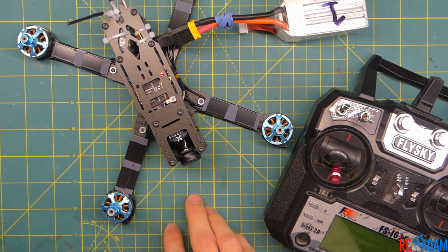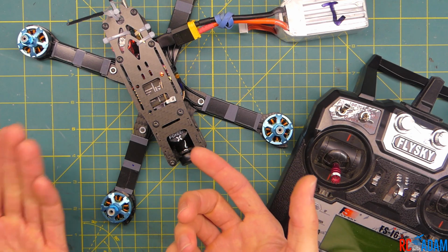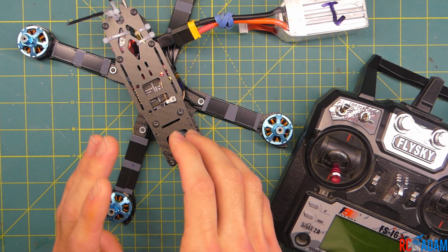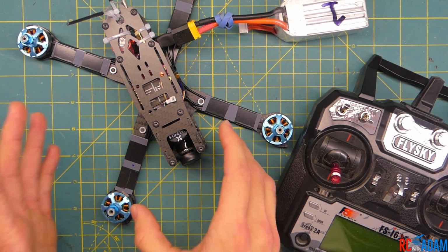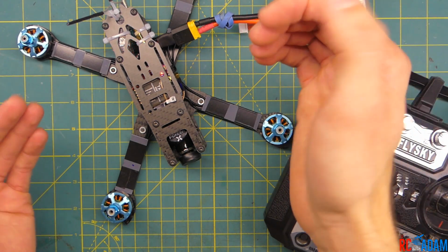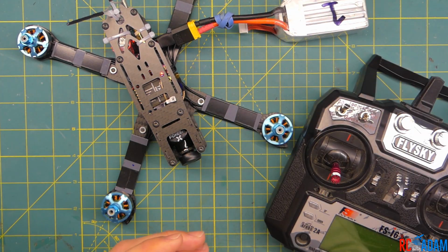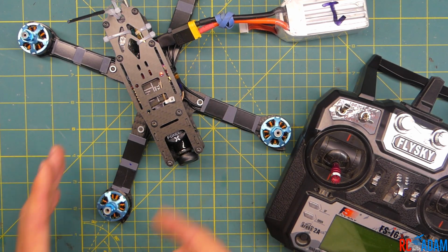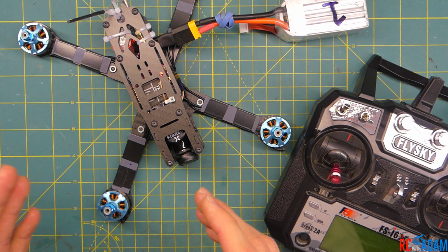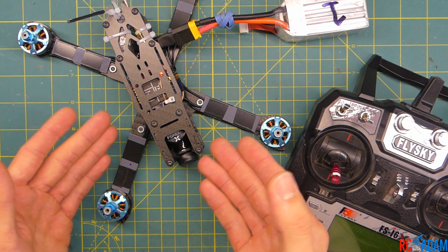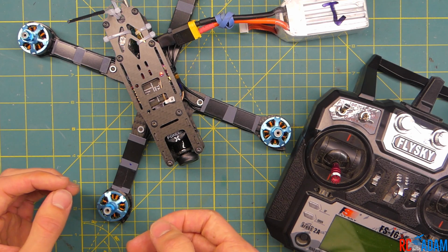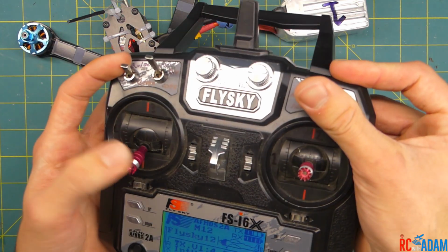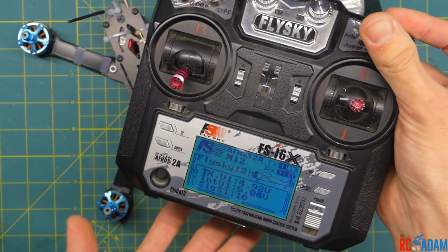But the important thing is it did shut off. The reason those motors were spinning up was because I had mine set to go to angle mode before it turned off. It went into angle mode, and the motors went back to an idle position, so that it will sort of land gently. And the reason the ESCs are beeping right now is because we had set the motor beep to beep until the connection was restored. So I'm going to turn this back on, and they should stop beeping. There we go. They stopped beeping.